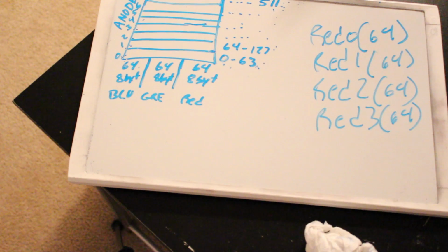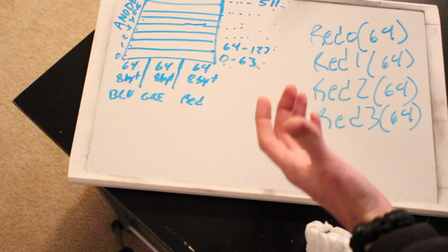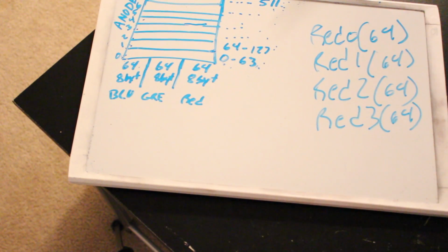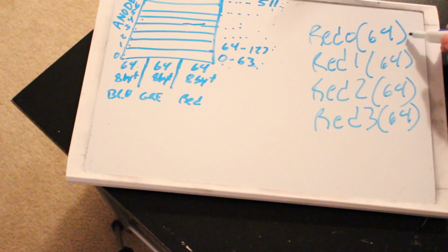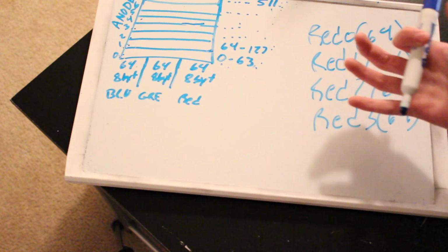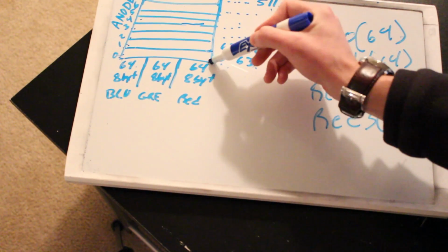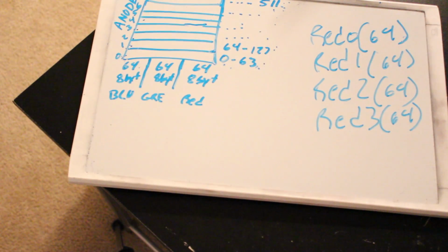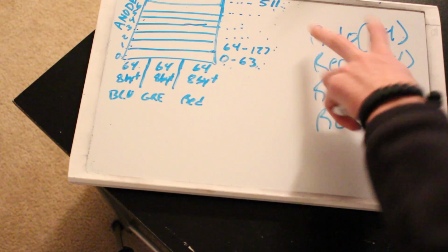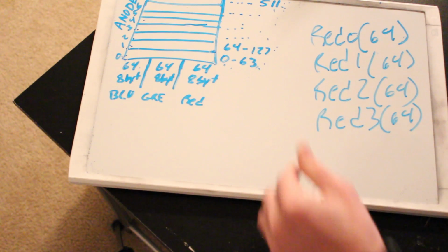Okay, so 64 bytes, there's 8 bits in a byte, can give you 512 bits. And it's exactly how it works. And we have to shift out 8 bytes at a time, since every time we go to the cube, what we do is only control a level here, okay, per color. So we shift out 8 bytes for the red, 8 bytes for the green, 8 bytes for the blue, okay? And that's how it works.